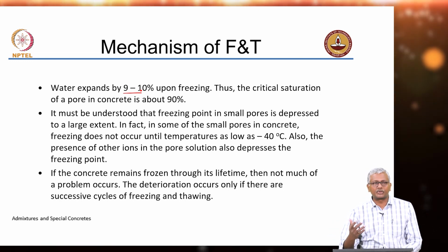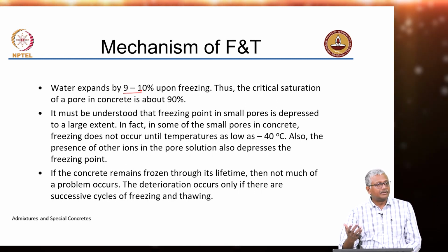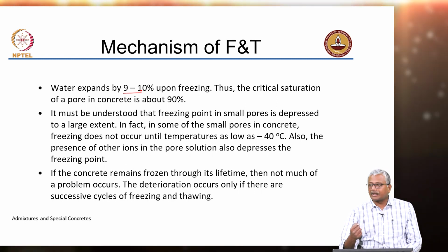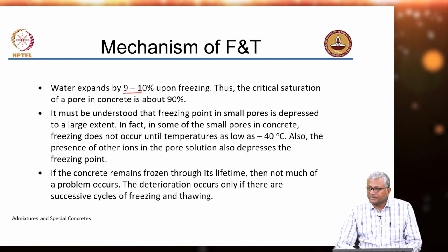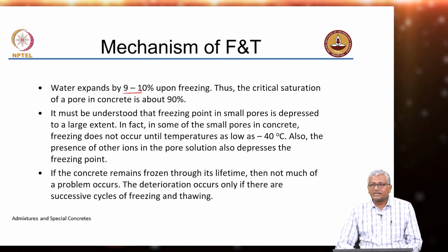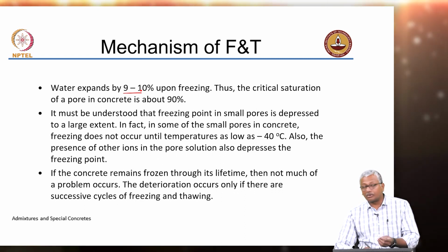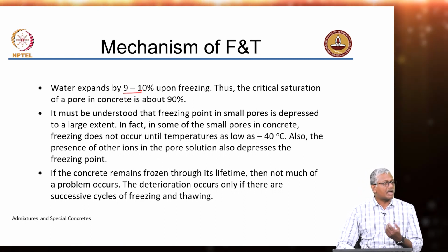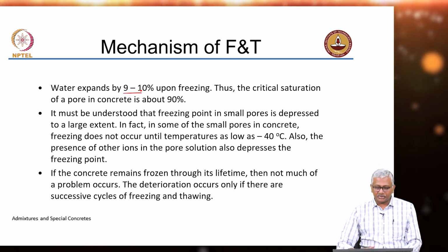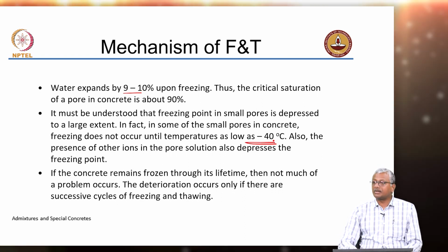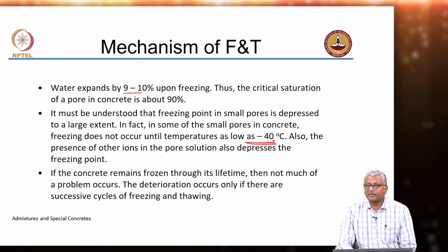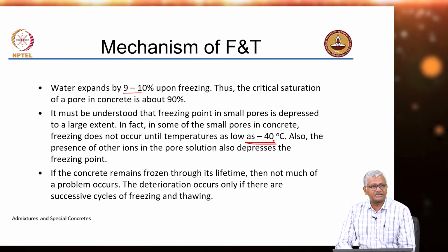That is why our pore solution is highly alkaline, and because the pore solution is not pure water, it depresses the freezing point even further. So, in some instances, freezing of water inside concrete may not happen until you reach very low temperatures, especially when you go to very small pores in concrete. Your freezing may not happen until minus 40 Celsius.